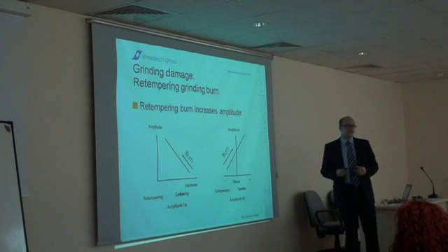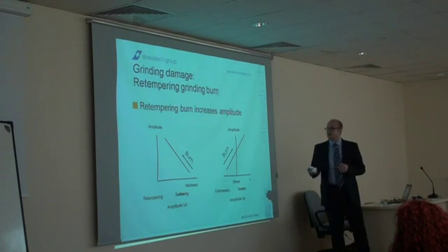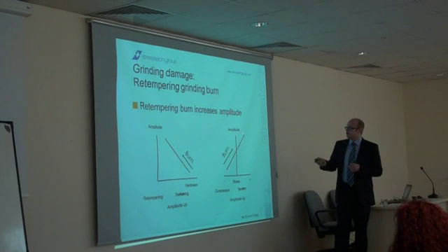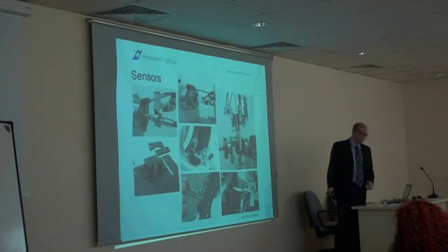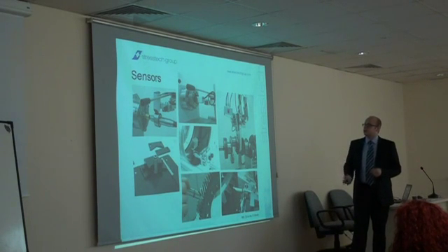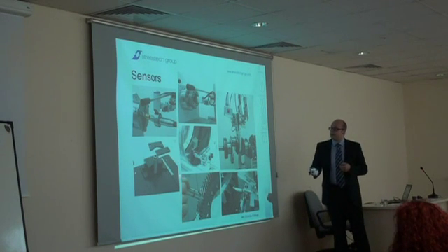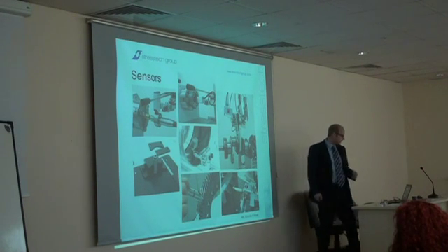And what happens, for example, if we have already hardened our sample and we grind it, and then we get grinding burn? It means that our hardness is softer, and we maybe get tensile stress, which means that we get high signal values again. That's why we are so good in our field, because our equipment is so sensitive to hardness and residual stress changes. That's why we are in many applications, for example, grinding burn detection.